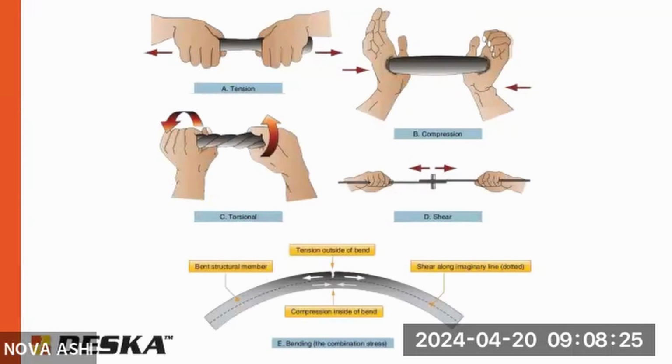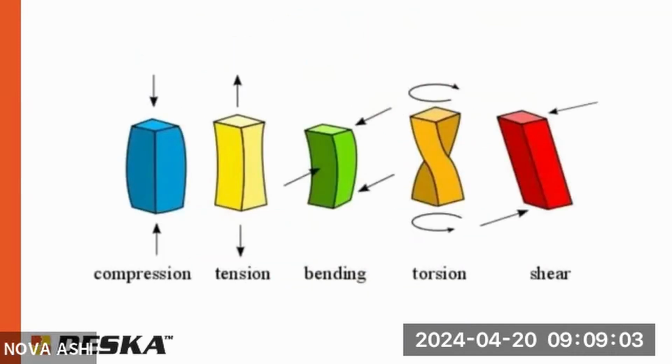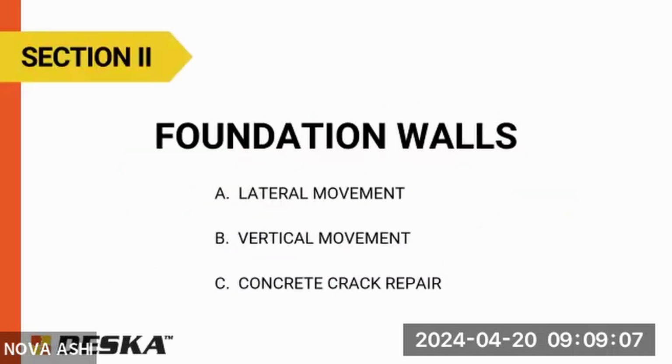Shear forces, an example of shear would be screws or nails, bolts, or the ends of a beam are in shear. And with a beam or with bending stress, you have a tensile stress on one side and a compressive stress on the other. And that allows it to bridge whatever you're trying to span. There we go. Okay. Just some more examples of that. We'll cruise through this here.